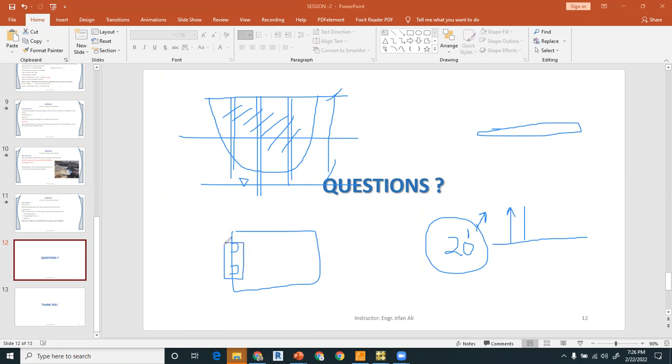to combine this footing and design it as a combined footing, right? So for example, if this is one column and this is the other column, and if you want to design it as an isolated footing and the area for the isolated footings comes out to be very large, then there is no restriction that this much thickness, this much spacing should be in between the columns to make it a combined footing. So you have to go for the combined footing automatically.